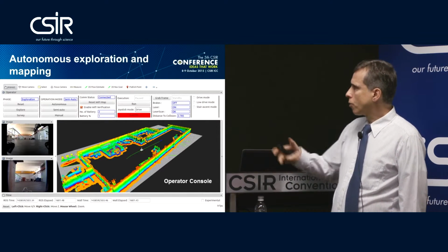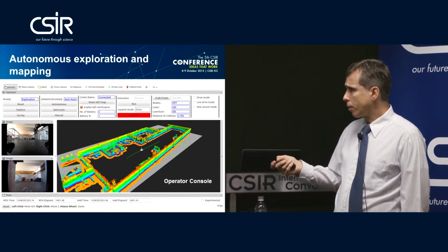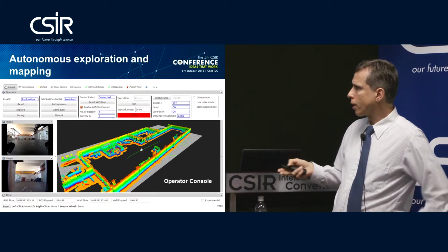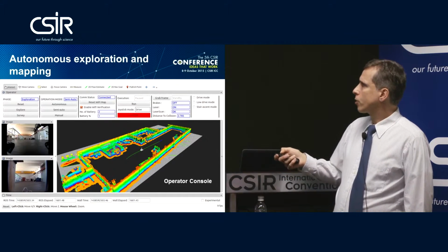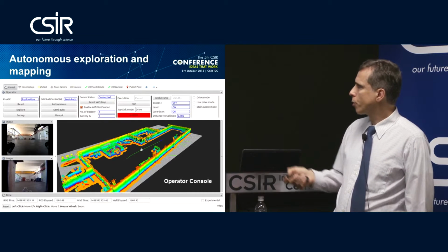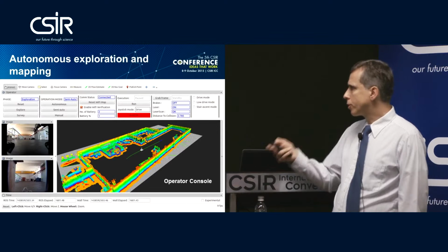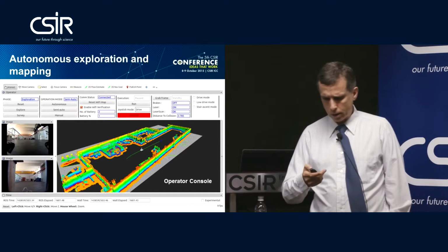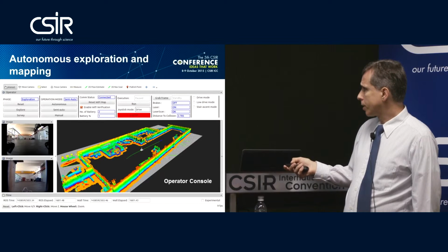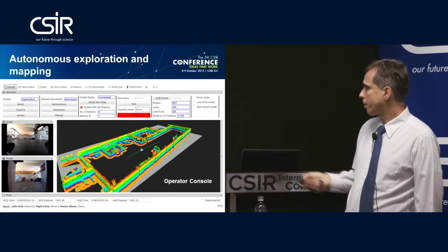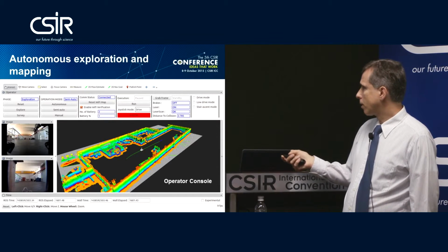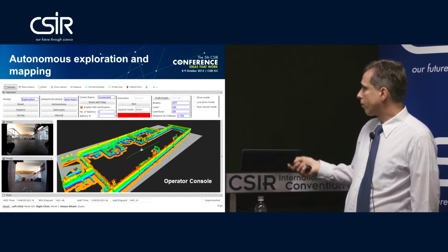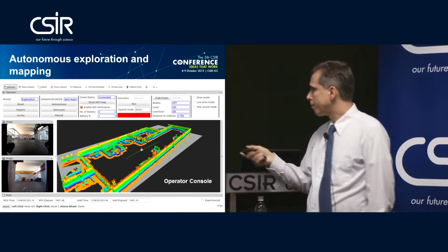Okay, we also have an operator console for this whole system. I mentioned two cameras from the robot. These are on the left-hand side here. There's the lower camera, which shows a kind of wide-angle view, and then the head cam. There's also some control here. The operator can control the motion of the robot, put it into autonomous mode, semi-autonomous, or manual drive. And on the right here at the bottom, we have the map produced by this robot. And you can see it's a three-dimensional map. The representation of the robot within this environment is made by this little white identifier here. And the path that it's traveling is this green line. What it's done now is it's scanned an environment through many of these scans. It's moved through the environment and scanned it, and this is the result.